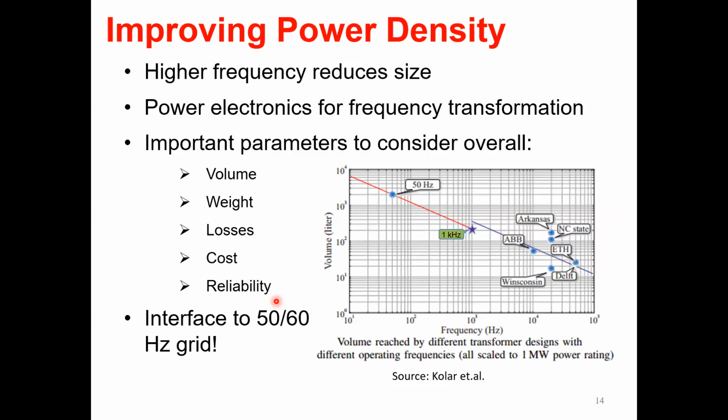So this is a partial answer to one of the questions which was discussed at the beginning. This is the primary reason for solid state transformers not coming full-fledged in the market. There are some isolated instances and occasions where people are using them, but full-fledged for higher power, especially maybe more than 1 MVA, it hasn't come to the market. It's mainly because of the reliability. And then there are concerns about losses again, but it's primarily the reliability.